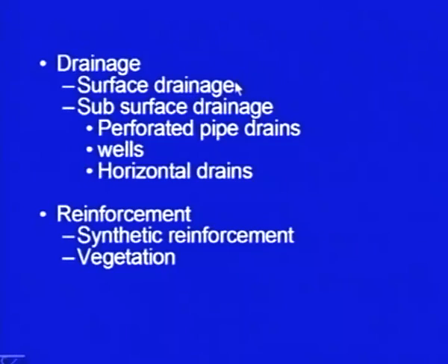A system of drains can be designed which will take the water to some safe place, and one can also provide subsurface drainage inside the soil. It can be done using perforated pipe drains. These pipe drains will collect water, and that water can be carried away to safer places.